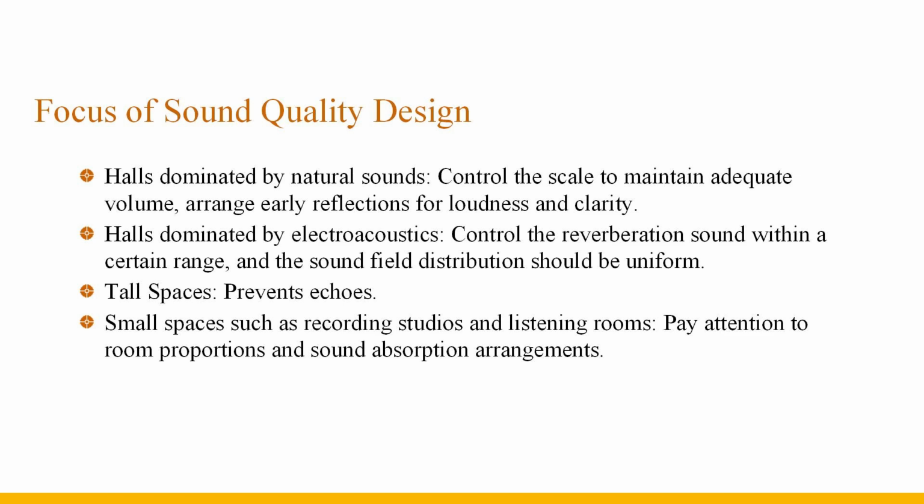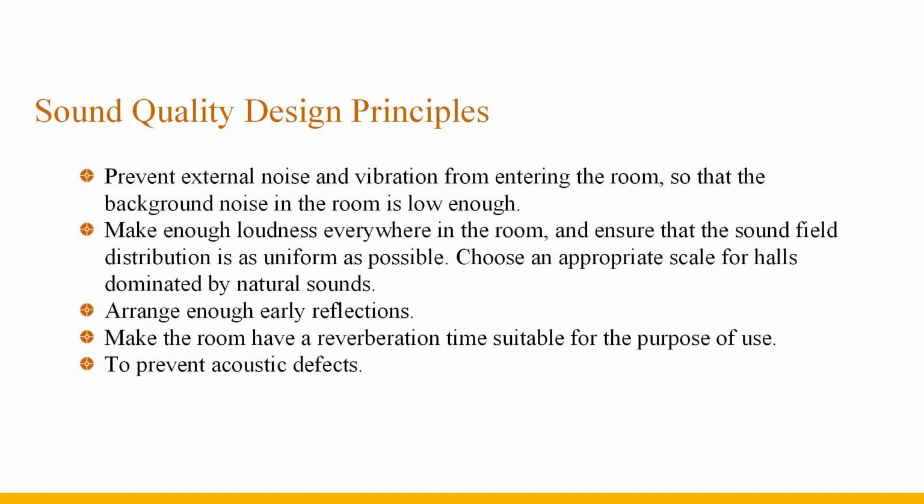For small spaces such as recording studios and listening rooms, attention should be paid to room proportions and sound absorption arrangements. In general, indoor sound quality design should follow the following principles. The first: prevent external noise and vibration from entering the room, so that the background noise in the room is low enough. The second: make enough loudness everywhere in the room and ensure that the sound field distribution is as uniform as possible. For halls dominated by natural sounds, pay attention to choosing the appropriate scale.